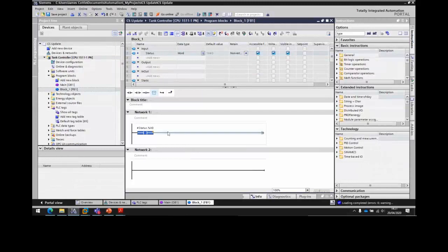However, this, of course, is fantastic, but this part here now isn't symbolically being addressed. We're now looking at things absolute. We're looking at bit 0. And what does bit 0 mean to me when I'm looking at this application code? Well, it doesn't mean anything. There is a way, though, of providing symbolic access even to the individual bits and bytes within this larger data type. And this comes when we're inside of function blocks, and it's something called AT construct.